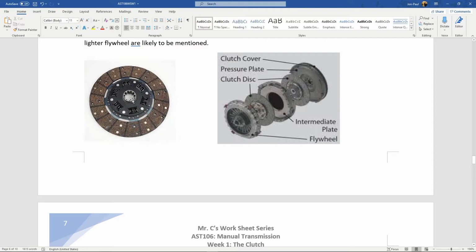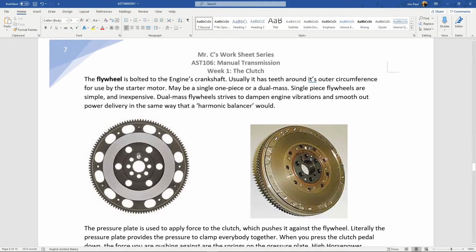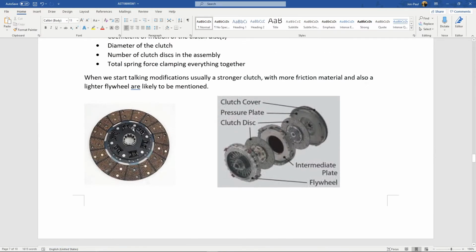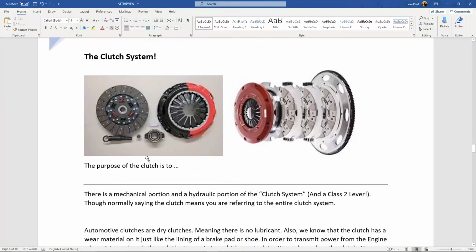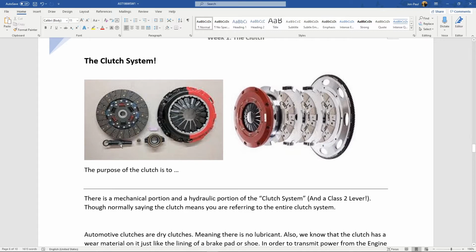So I want you to think about trying to assemble all of this without that clutch falling or sliding, and then when you have the task of trying to stab the engine and transmission back together, you've got to hope that this clutch didn't move. Sounds difficult? Yes, nearly impossible. That's why they sent this nifty little alignment tool. So let's walk through this together so that you're ready when you hit the dealership.